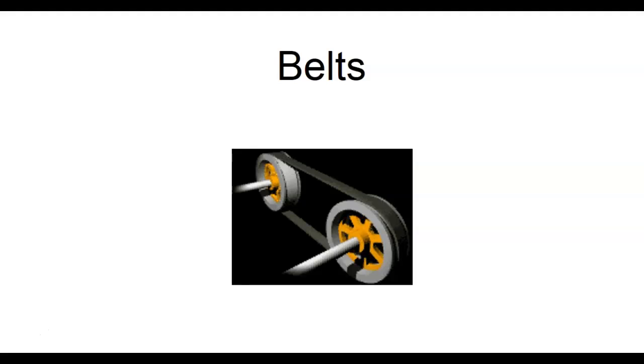So how do we calculate the mechanical advantage on these? We can't use teeth because they have no teeth. So how will we calculate that? We can use diameter, right? Or the radius, so we can measure that. Make it the output diameter over the input diameter.